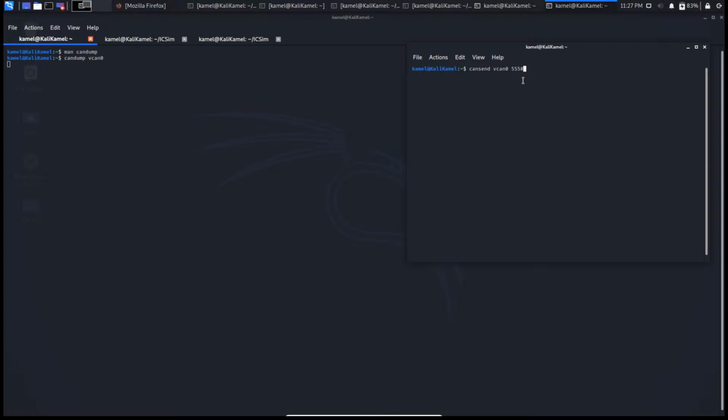So popular options for this, for demo purposes, include DEADBEEF, C0DECAFE, right? It's just a silly sentence that you can write using the hexadecimal numbers, right? 0 through 9 and then A through F. So if I hit enter here, we will see in real time that this message gets transmitted onto this virtual CAN bus.